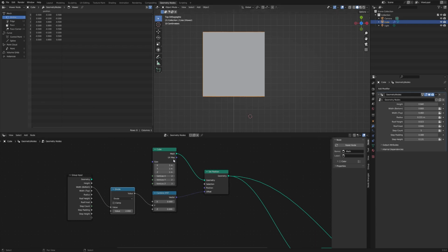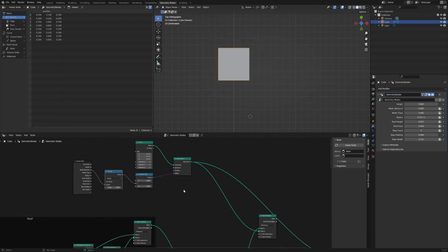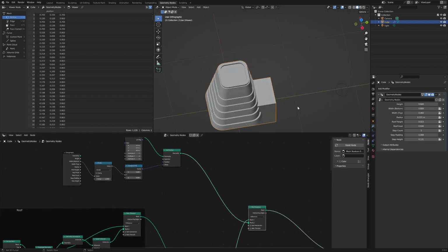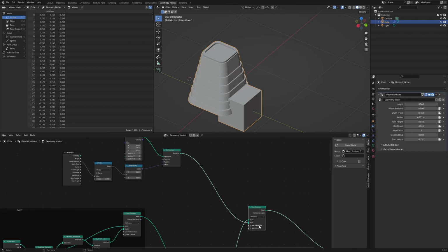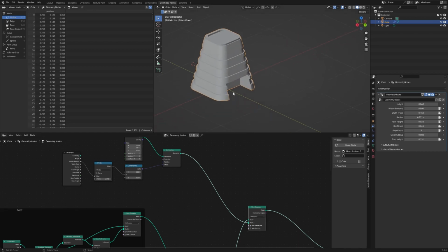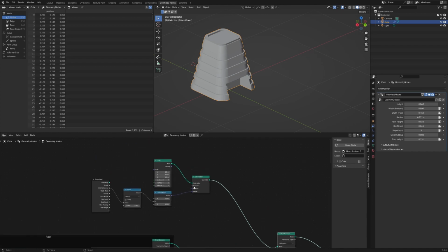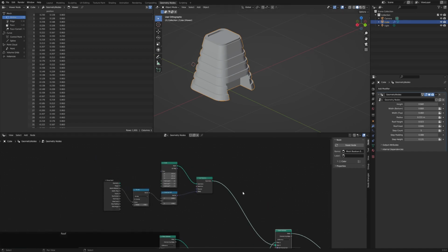So now you'll notice if I resize this, a little shortcut by the way, hold down shift, drag all 3, and then you just have to type 0.5 once and it changes all 3 dimensions. So we've now got our mesh boolean, which is again not working. So we just click the self-intersection back on again, and that seems to be happy. So yeah, I'm really not sure. It's quite annoying, but it does work if you click self-intersection.